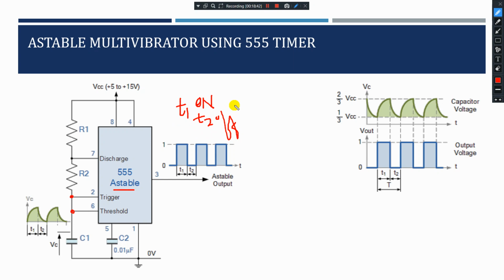So in the 555 oscillator circuit, as we have seen here, pin number 2 and pin number 6 are connected, we know that, allowing the circuit to re-trigger itself. So it will allow re-triggering of itself on every cycle, allowing it to operate as a free running oscillator. So it is an oscillator, it is generating some pulse. Because 2 and 6 are shorted, it will start triggering itself by T on, T off, T on, T off, T on and T off. This will continue.